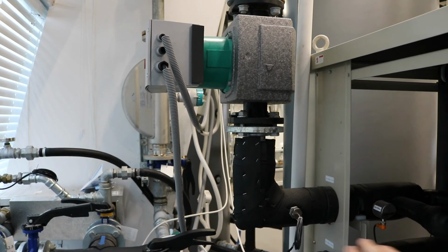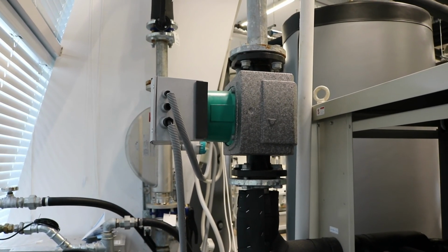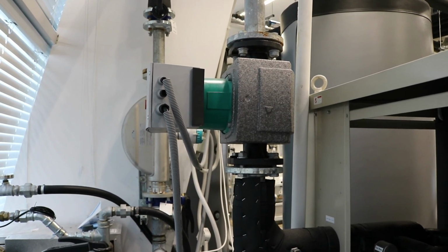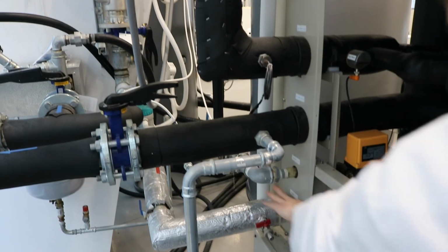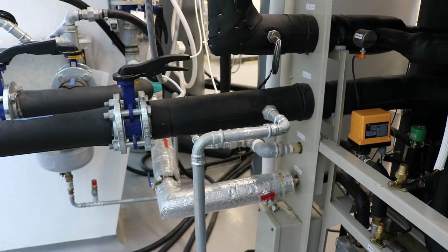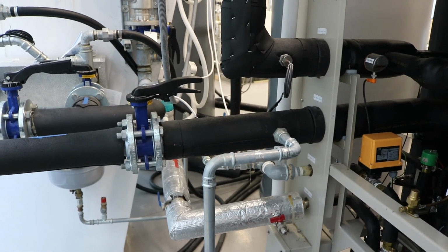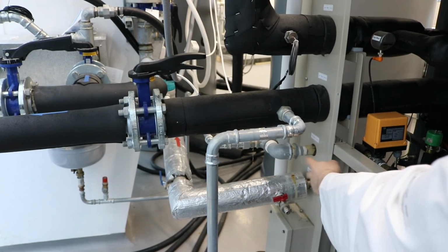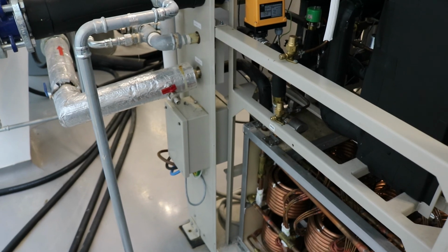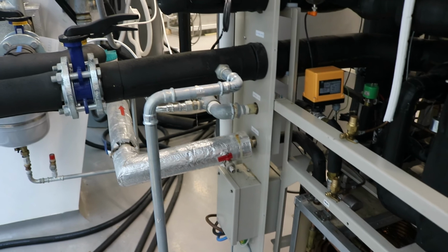As you can see, we need a big pump to deliver this water that goes through the evaporator and cools down. Here lower you can see the upper source pipes. The pump is over there behind the wall. You cannot see it now. As you can see, it goes right into the gas cooler when it takes energy from the cooling the CO2.